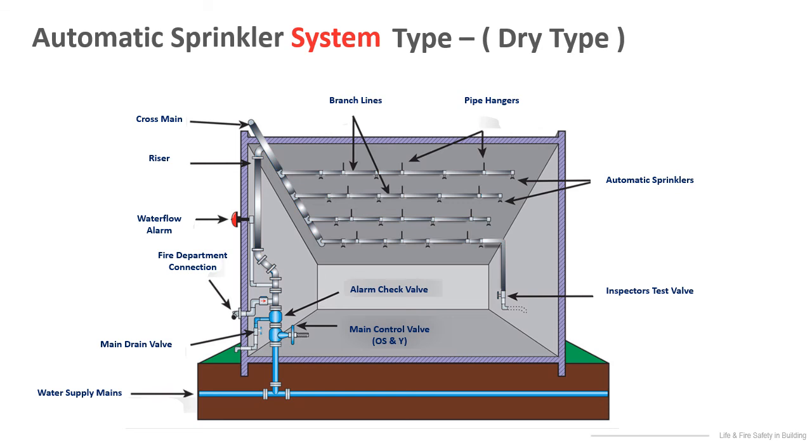So, dry pipe systems are very similar to wet pipe systems, with one major difference. The pipe is not constantly filled with water, and instead the water is held behind a dry pipe valve, usually some distance away from where the sprinklers are located. Like a wet pipe system, when the temperature at the ceiling becomes hot enough, the glass bulb or fusible link in the sprinkler will break.